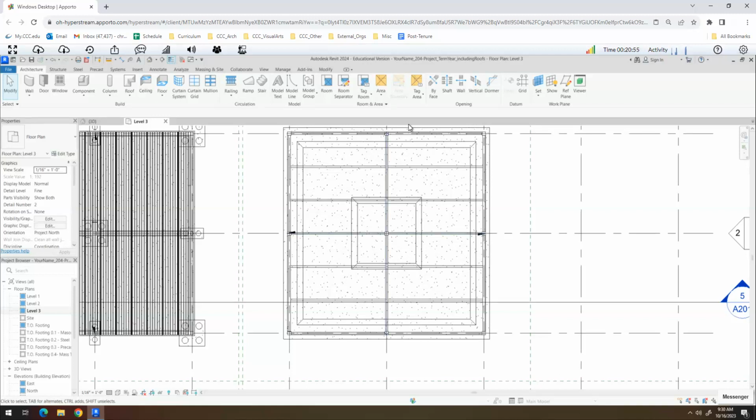One is somewhere on the interior of the roof surface, let's say right here, for example. Another one is at the perimeter. So you can basically have a low pitch that takes the roof to something called a scupper.